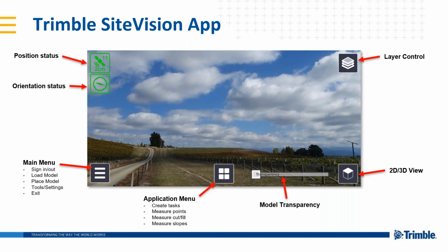So when you start the system, it takes a few moments for the GNSS to locate itself, and you need to wait for the GNSS to have converged down to the desired accuracy before you can start using any of the other tools. So that's why it's a sort of traffic light system. It goes from red and then ultimately to green once it's reached the desired accuracy, and you have to wait for that position to go green before you can use the rest of the system.